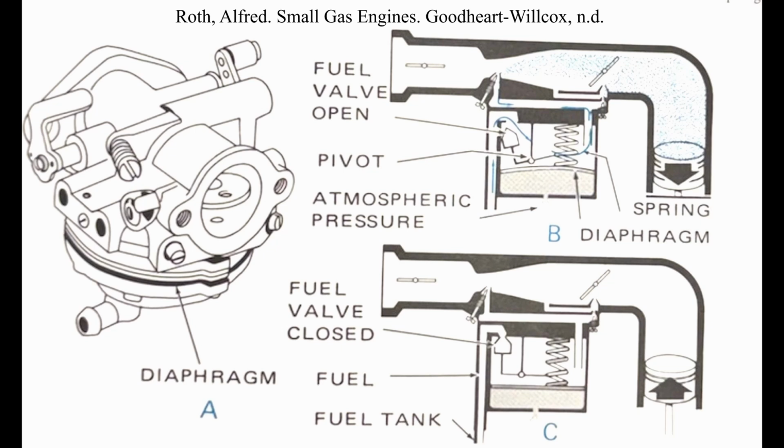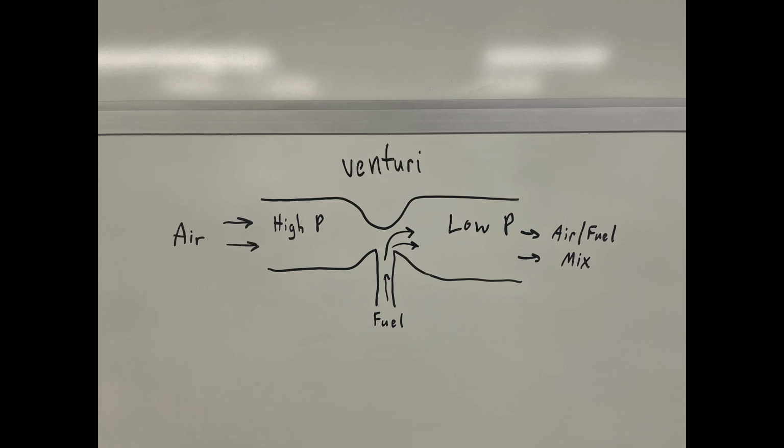into the carburetor. There is a venturi within the carburetor that speeds up atmospheric air taken in from the outside by decreasing the cross-sectional area the fluid has to travel through. By the continuity equation, the fluid velocity must increase in order to conserve mass flow rate. Due to Bernoulli's equation, a pressure drop occurs, which pulls fuel along the carburetor and mixes it with the air to send to the engine. This engine, of course, is then connected to a shaft, which allows the weed whacker to spin.